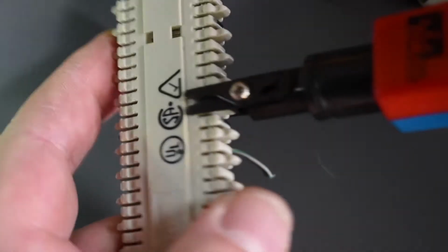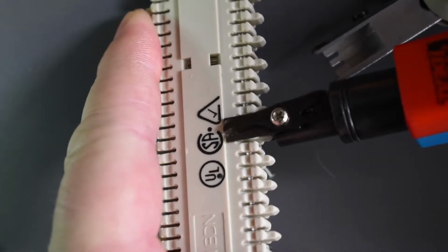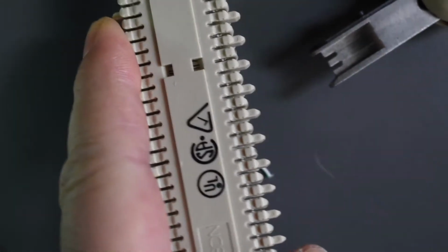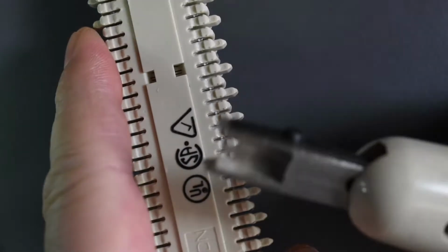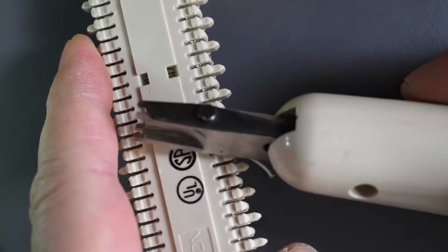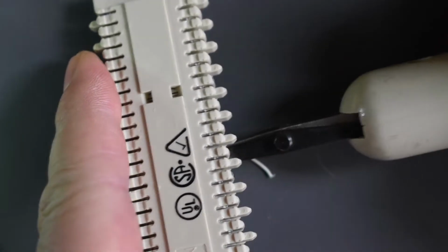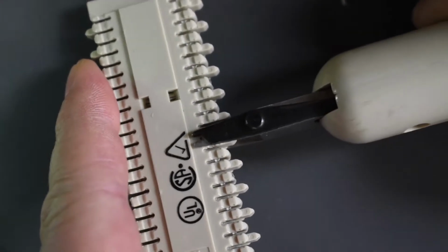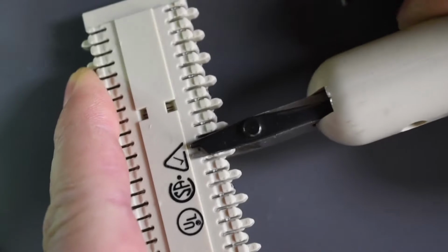Usually the punch down tool for BIX involves a moving knife. When I punch it here, see, the knife moves. And this one is the same. It's BIX, just made by a different company. You can see that the knife moves, but in a different way.